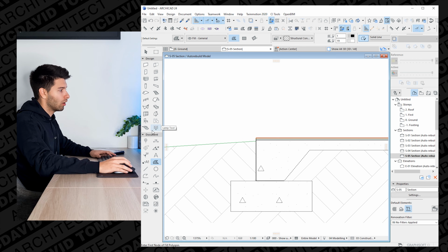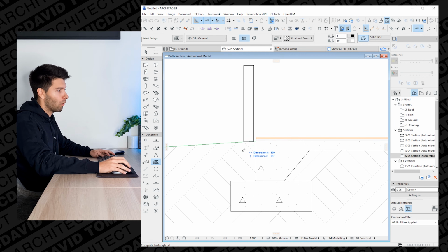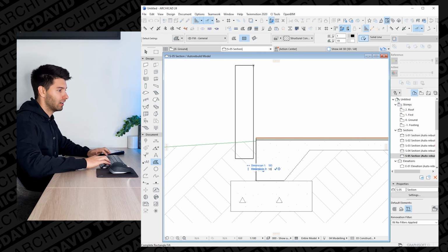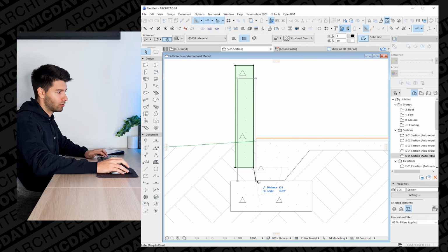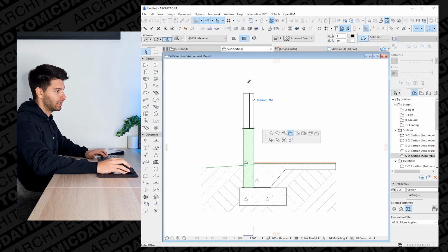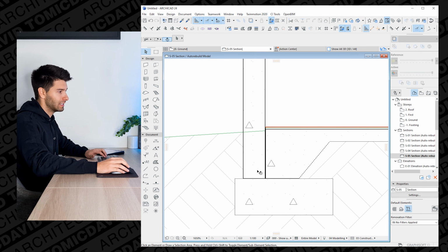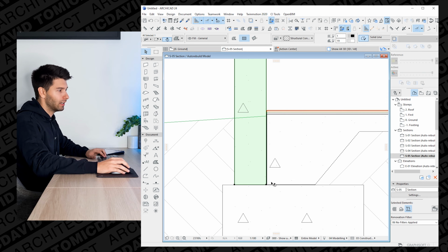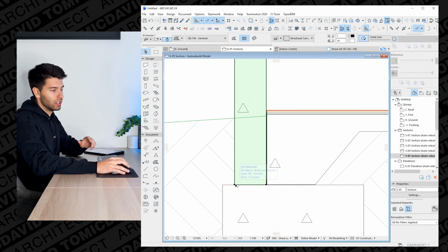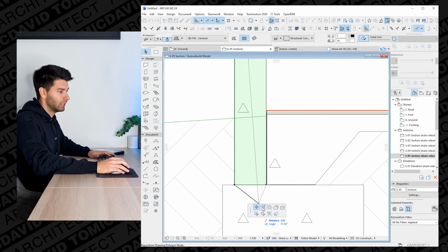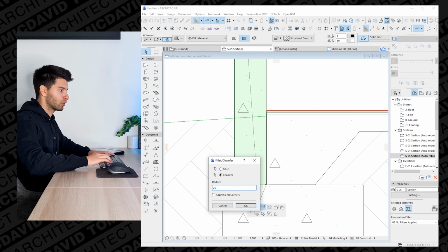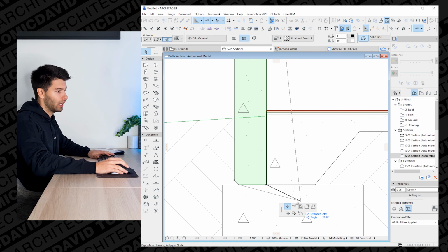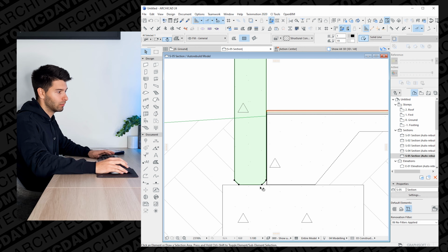because it is structural concrete, and I'm going to draw a 180 thick by 1 meter concrete slab. So let's drop that in there. I'm going to extend that a little bit higher just so we can see it properly, and I'm then going to chamfer these corners. There's a number of ways you can do that. You can click on this, go to the chamfer fillet, go chamfer, and let's call it a 25 mil chamfer, and we'll do the same principle here.